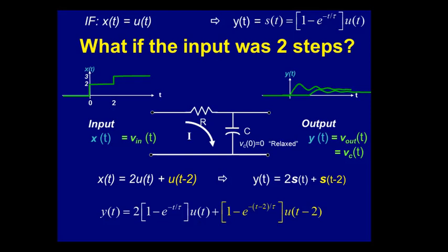That's using linearity and time invariance, superposition, to infer the output using a known input. That's the method we want to generalize today. That's when we want to push that to the max. Does everybody understand what we're doing there and why we're doing each of those, how that works? That's linearity and time invariance restated. This is because of linearity, I can scale. This time shift on the input is the same time shift on the output. That's time invariance. The fact that I can add inputs gives me added responses. That was additivity of linearity. It's all those properties together we're taking advantage of here.